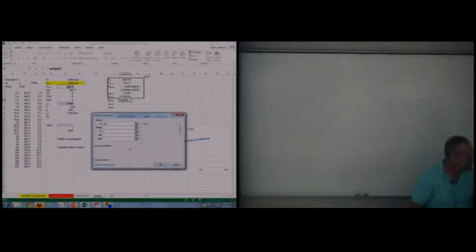They told me they calculate them all at arithmetic average pressure. I like that clever technique of copying a cell and then changing the name. And they didn't tell me if there's any impurities, so I'm going to assume they're all 0.